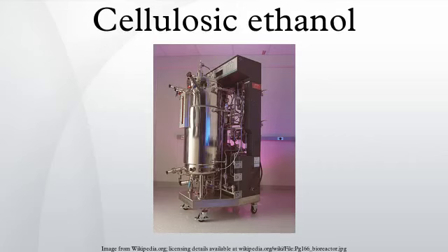Hemicellulose to ethanol. Studies are intensively conducted to develop economic methods to convert both cellulose and hemicellulose to ethanol. Fermentation of glucose, the main product of cellulose hydrolysate, to ethanol is an already established and efficient technique. However, conversion of xylose, the pentose sugar of hemicellulose hydrolysate, is a limiting factor, especially in the presence of glucose. Moreover, it cannot be disregarded as hemicellulose will increase the efficiency and cost-effectiveness of cellulosic ethanol production.